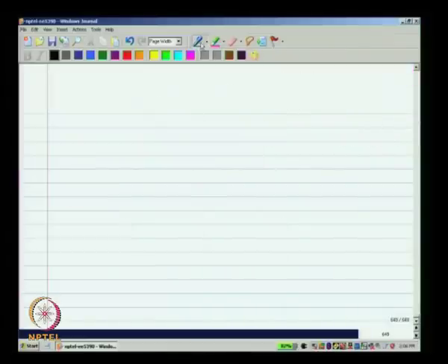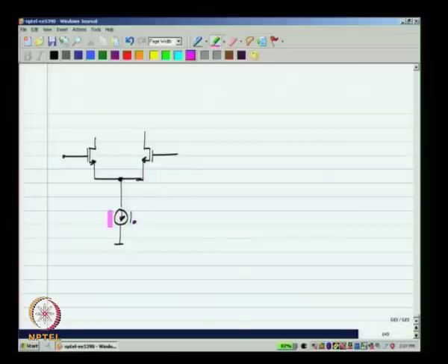Now, the next thing is that one of the uses of a current source is to bias a differential pair or a transistor. For instance, if we bias a differential pair like this with I naught, the Gm, the transconductance of this differential pair depends on I naught. Now, one of the interesting things is to design this in a way that keeps the Gm constant.